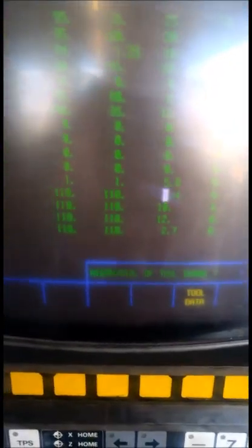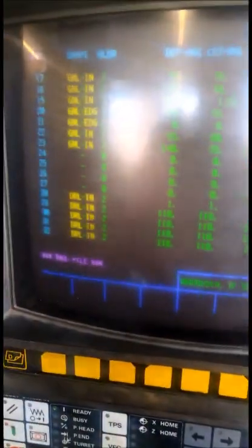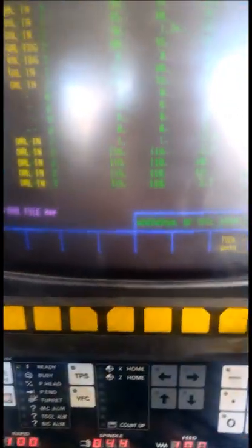So you have just your point angle, your tip angle, being 118, and then just the width of the drill bit. This really only comes into play when you're running a simulation, because if you tell it it's a 6mm in there and you're trying to drill a 12mm hole, the simulation will show a 6mm hole. That's really all that does.